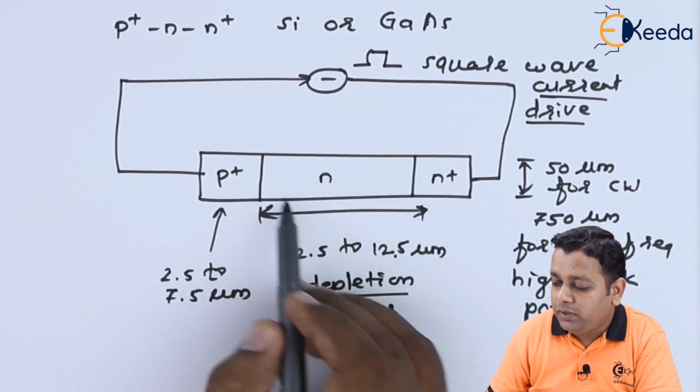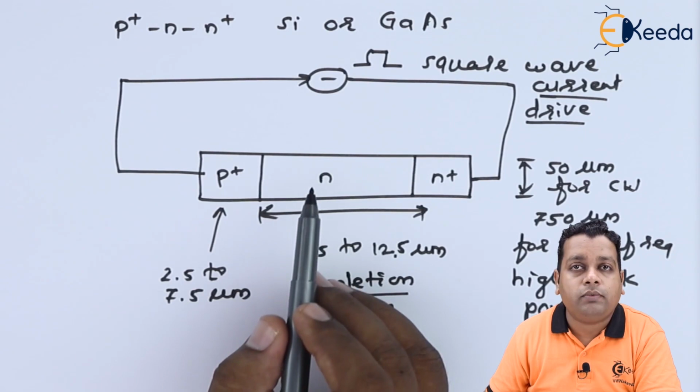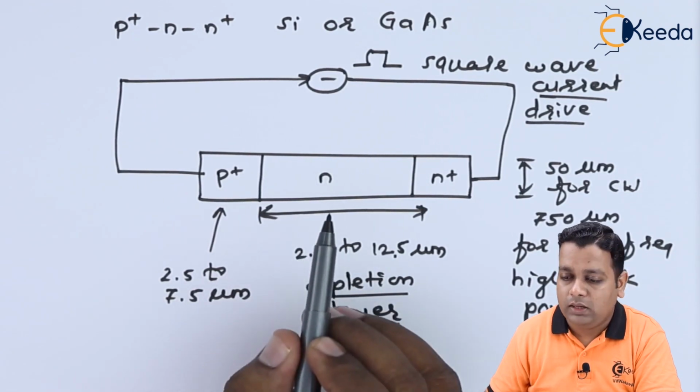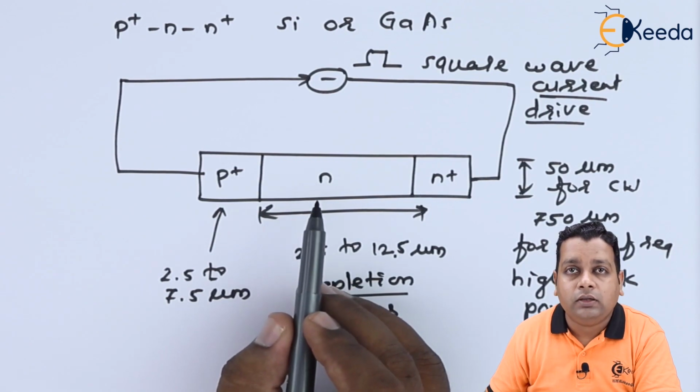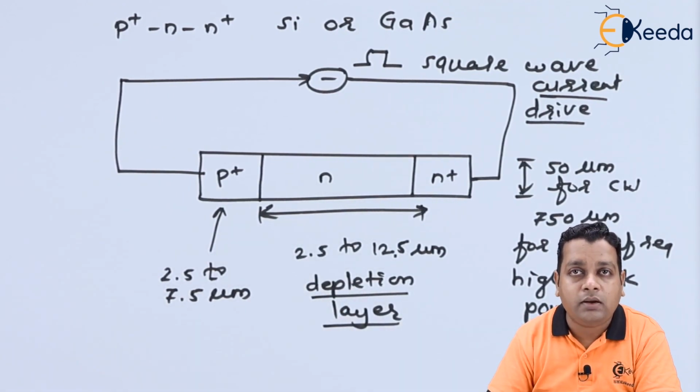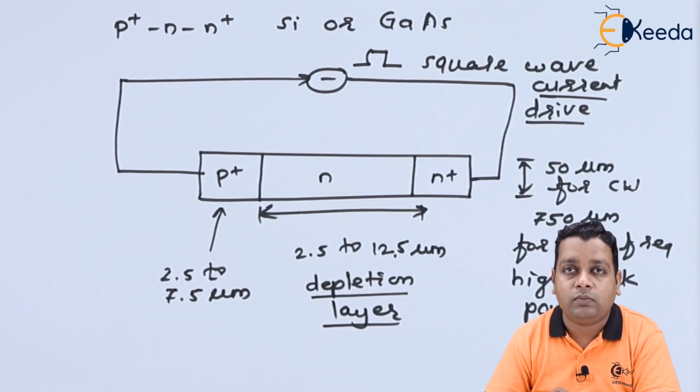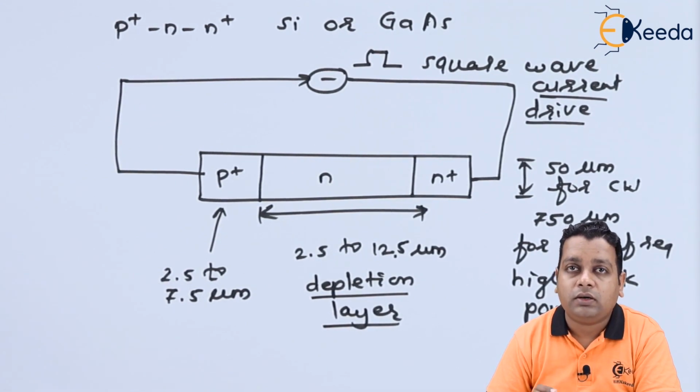So it will be completely filled because of the avalanche plasma generated here, and it will be trapped inside the low electric field region. Hence we name it the trapped plasma avalanche triggered transit time device.